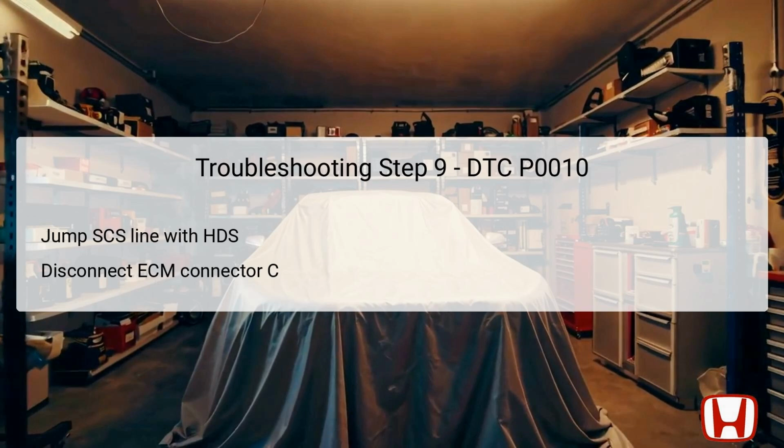After performing this jump, the technician should disconnect the ECM connector C, which has a 44-pin configuration. Disconnecting this connector allows for isolated testing of the electronic control module and its connections, laying the groundwork for in-depth diagnostics of potential problems. Understanding the relationship between the SCS line and the diagnostic tools is crucial for efficient troubleshooting.